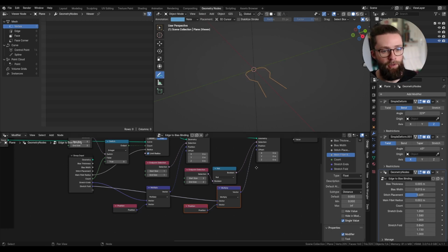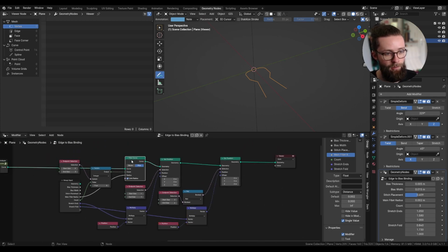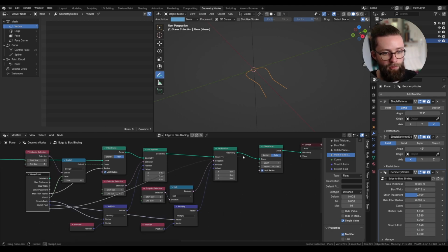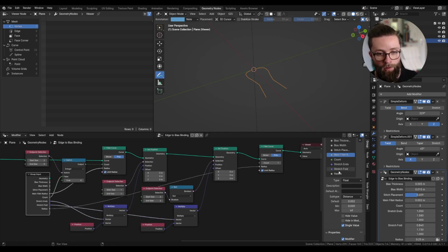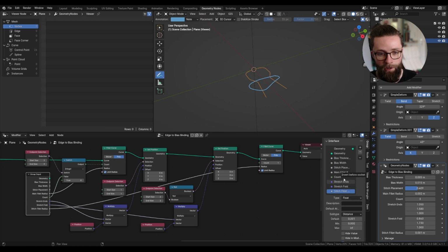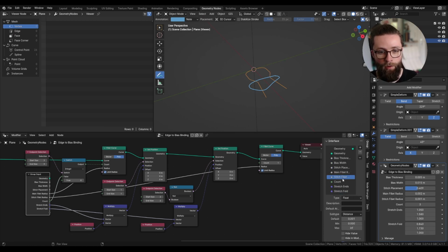And this works already pretty well, but now let's add the final step with a new fillet curve to smooth everything even more. Here the radius will be a new input value, which I am going to call stitch fillet radius, because I only want to reduce those 2 points where the stitch placement will be on the bias. This will also be a single value, and I will also put a default value of 1 mm. Here I am just reordering it near the other fillet value, and for the count I want to rename it fillet's resolution.